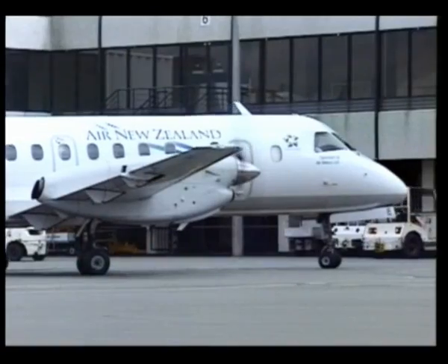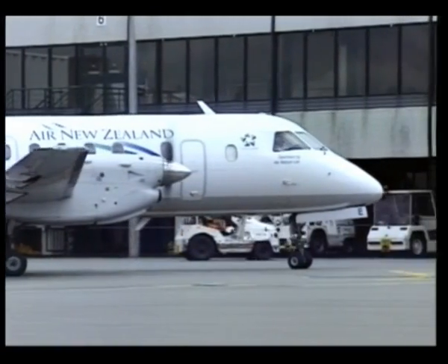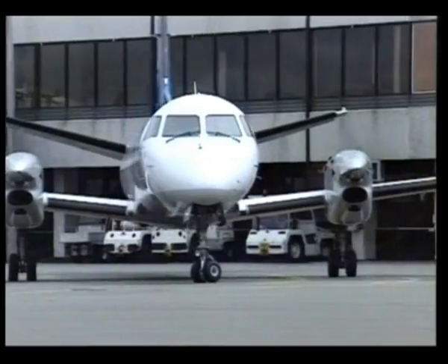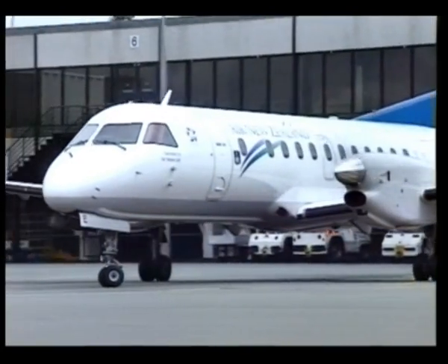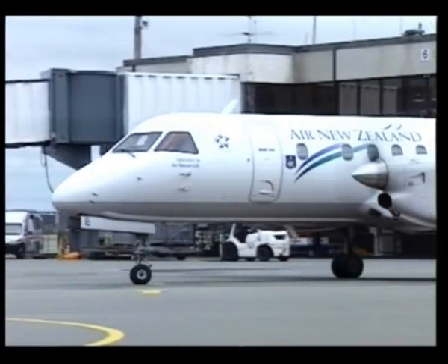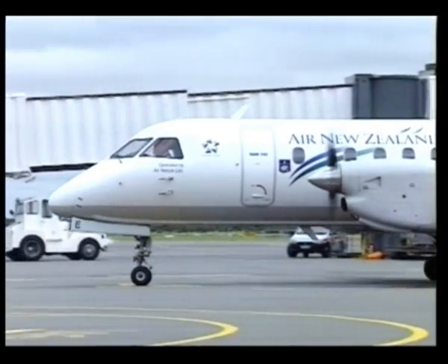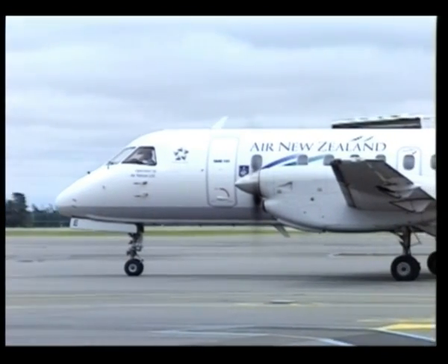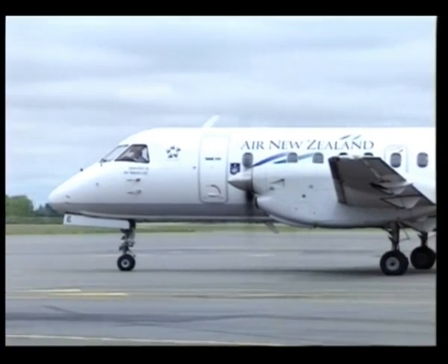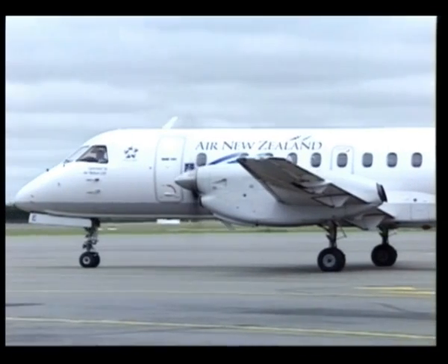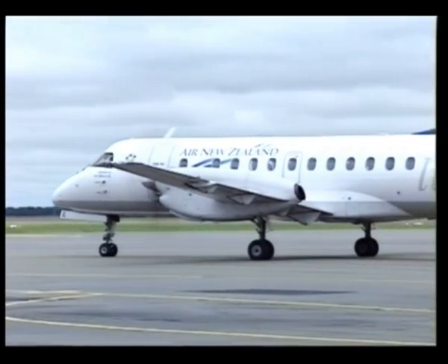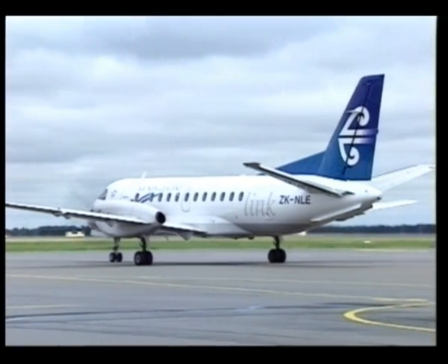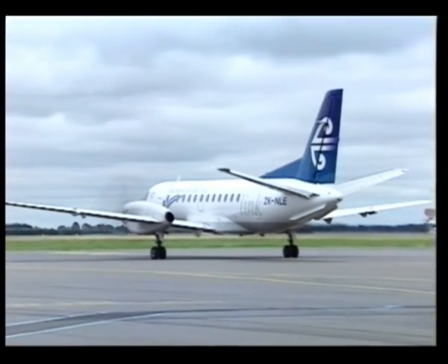We better understand the relative performance of different types of turbine when we understand thrust and propulsive efficiency. The force that propels an aircraft is known as thrust, and it is the amount of static thrust a jet engine produces by which it is rated, just as a piston engine aircraft is rated in horsepower. Thrust is a function of the altitude and airspeed of an aircraft and of the engine control setting. It is this thrust force that accelerates the aircraft and balances drag.